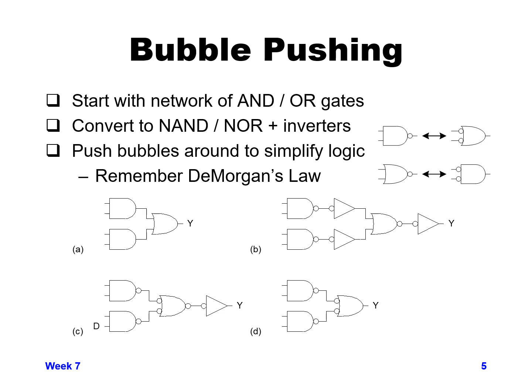So that's how we transformed from example A to example B, or example 1 and example 2 of the previous two foils. From the upper left A down to lower right D, we get two NAND gates followed by a not OR, which again is a NAND gate. You can see that depicted in the very upper right, where the bold arrow shows that a NAND gate is the equivalent of a not OR. If you didn't quite catch this, maybe go through the foil again, but hopefully this makes logical sense to you.